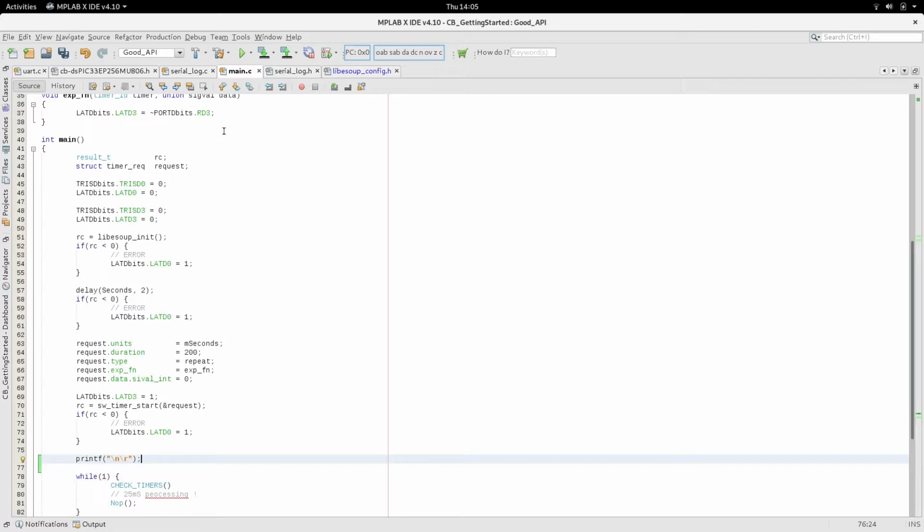So that function, Microchip have actually implemented that function. The libraries you get with the DSPIC33 include a printf. Now that printf assumes that you're outputting on the first serial port, and it is quite complicated and prints out a lot of different types of information.